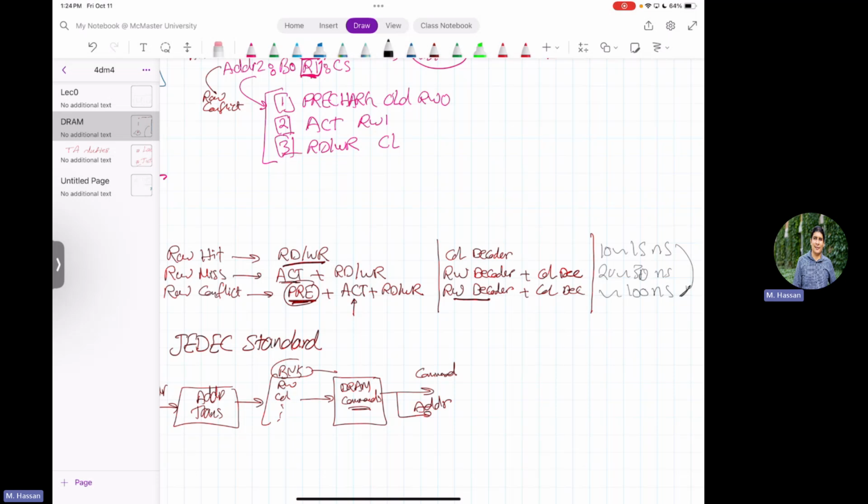So SRAM is random access mostly because in caches, whether you target set 0 or set 1, it takes the same amount of hit time. But in DRAM, whether I access this address or this address, there's a 10x difference in latency. It's not at all random access. So it's a very ironic name. It's not in fact satisfying the truth. DRAM is not truly random access. There is a 10x difference in performance based on what address you are targeting at the moment.